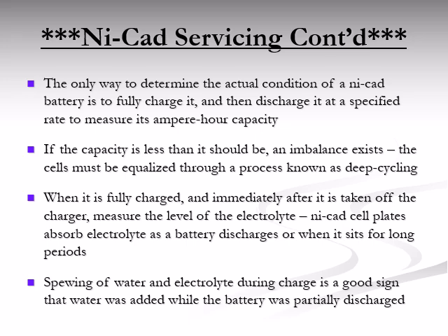Lastly, if you observe water and electrolyte spewing from the battery during charging, it's a clear sign that water was added prematurely while the battery was still in a discharge state. This overfilling leads to expansion during charge, causing overflow. Proper servicing ensures safety, longevity, and optimal performance of the battery system.